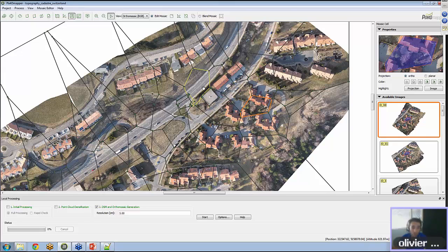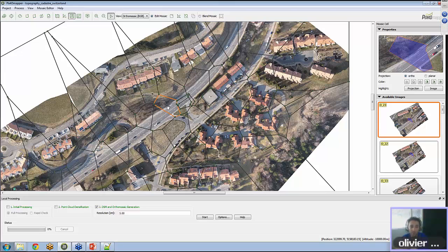And at the same time, when we have created that P4S file, it has been created with what we displayed at the beginning. We have now done some modifications, so we have to save them. We go to Mosaic Editor and we click on Save Mosaic. Then that P4S will be modified and will have the modifications that we have done. We have one option that we don't activate by default, that is Auto Save Mosaic. If you select it, now we can see that it's selected. Every 5 minutes, the mosaic will be saved to that .p4s.